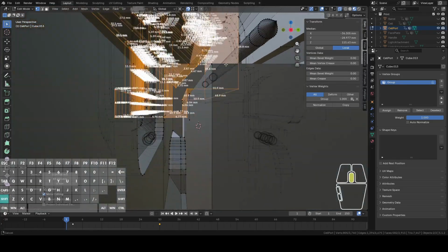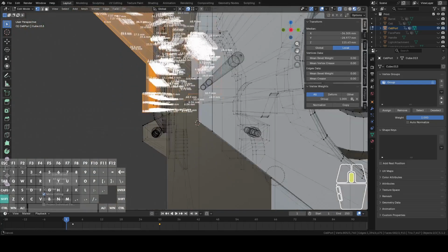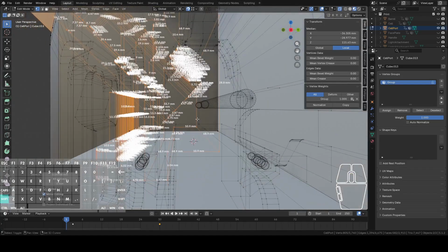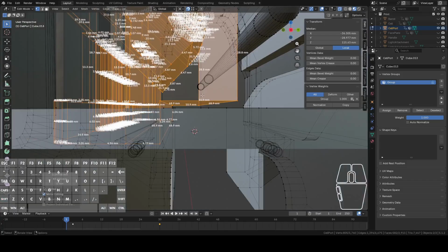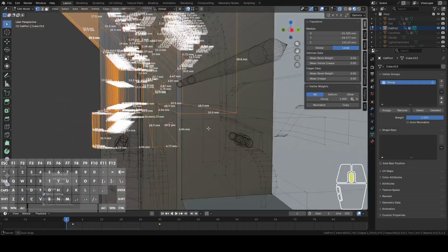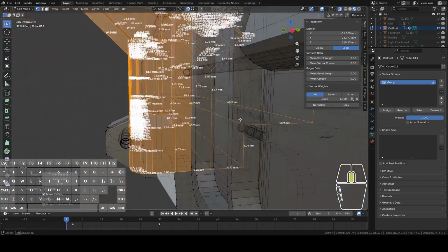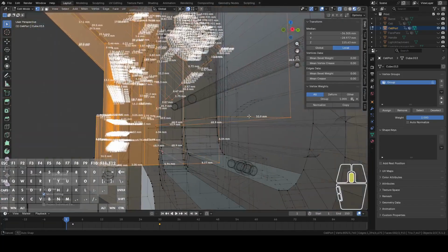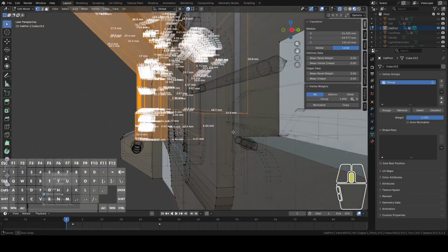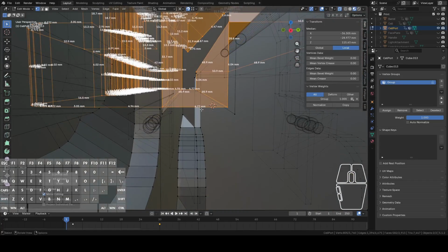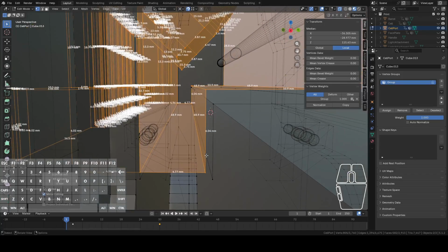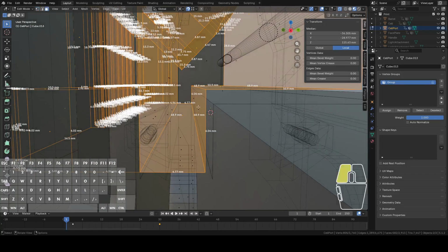Oh no. But this is going inward, so it's going to need a little room in there to print that step. Otherwise, this is like just 1 pixel wide here. So I guess we're going to need to do something about that too. So this part needs to come out maybe 2 millimeters.